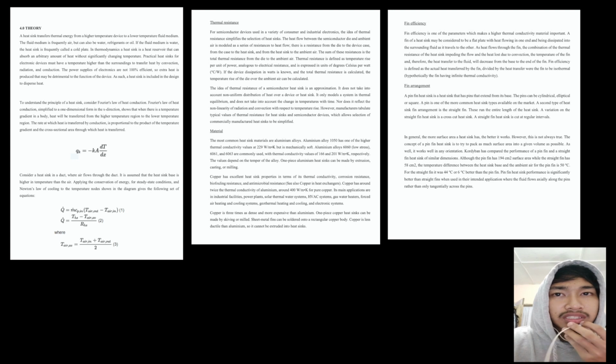Next, to understand the principle of a heat sink, consider Fourier's law of heat conduction. Fourier's law of heat conduction is simplified to one-dimensional form in the x direction. It shows that where there is a temperature gradient in a body, heat will transfer from the higher temperature region to the lower temperature region.